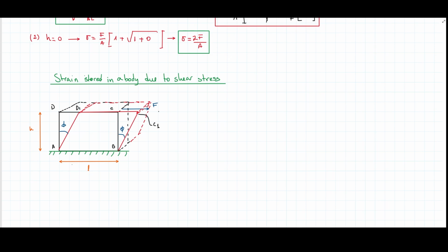Now let's see what's the relationship that we can get from all of this. So we know that the shear stress equals to the tau. Again, keep using the key. Force divided by the area. But who's the area? So we could call that the depth of this body is like this, and then this is B. Then the area would be B times L. So shear stress equals to the force divided by L times B.